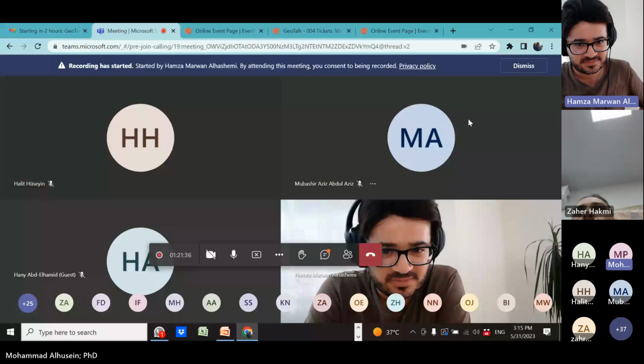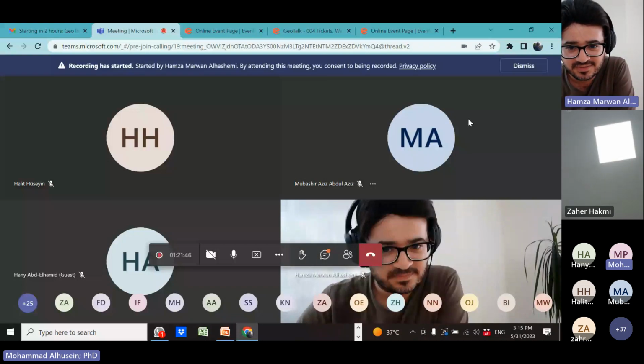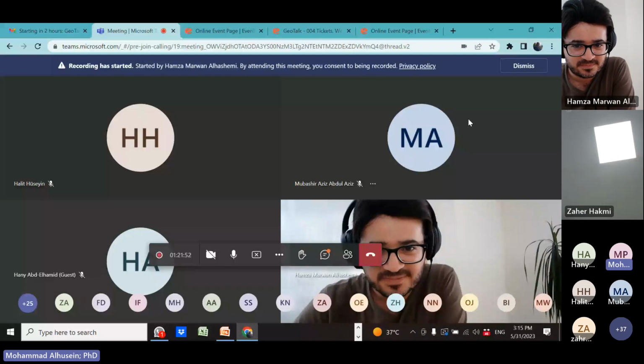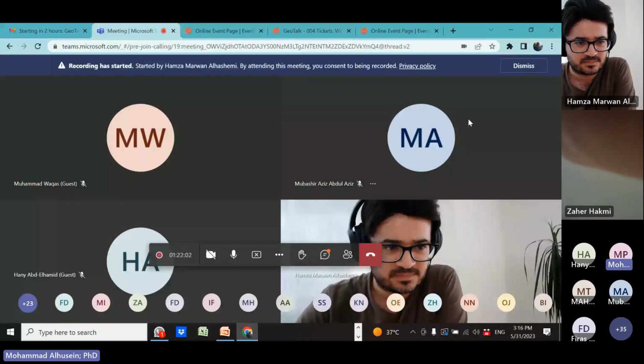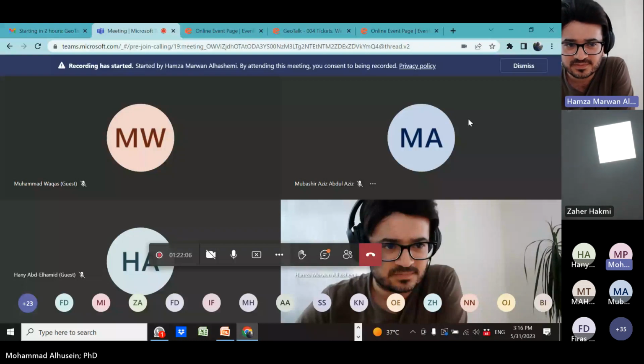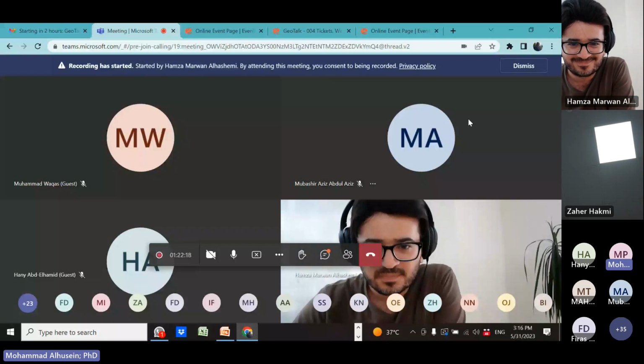pH? No, pH cannot. No, never, ever. You have to do carbonate content. You have to do, for example, gypsum content. You have to do TSS, total soluble salts, the TDS, for example, total dissolved salts, etc. No, you cannot. pH, by the way, and chloride and sulfate are for the concrete durability, not for the soil durability. I told you, no one cares about the durability of the soil. This is the problem. Indeed.